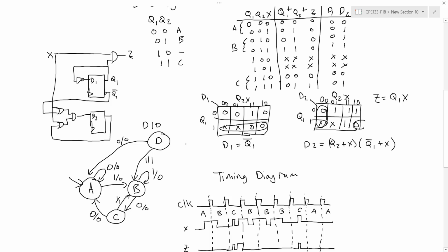For some circuits though, and some sequential implementations, you might have your don't care states with no path or no connection back to the original state diagram, the finite state machine, and instead they might have a cycle in themselves. So depending on the application, this could be bad. If I have an error and I get into one of these states, I'm going to be stuck not operating the right sequence. So for this reason, we sometimes make sure that there is at least one path from our don't care states back into the right state diagram so that the circuit could eventually recover. And this is sometimes called a self-starting circuit.